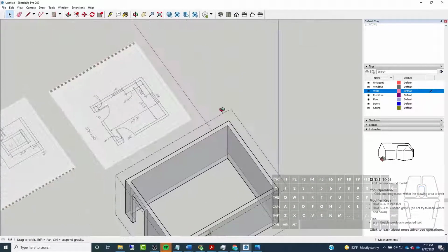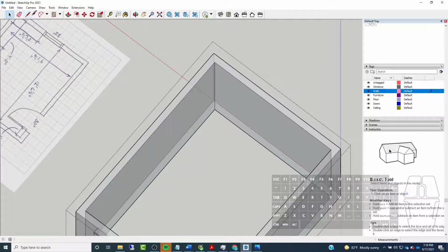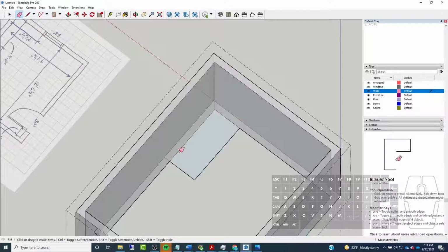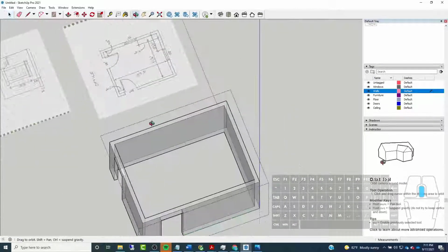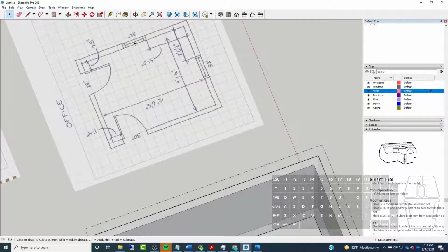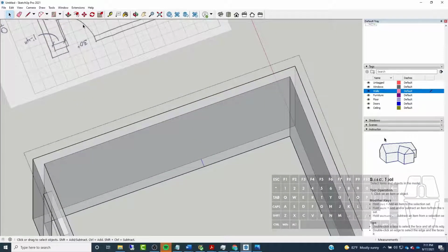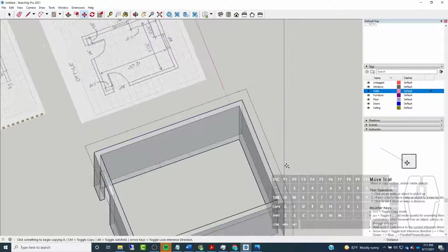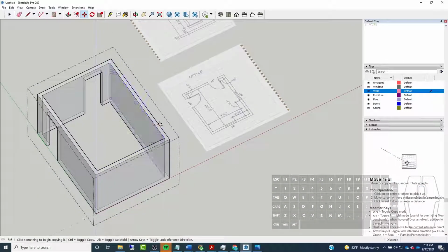Okay, so for my window now, starting at this wall, I'm going to do my dimension of 4 feet out. Then my casing, 4.5 inches. And then I'm going to draw my line through and just get rid of the extra pieces. So I just have my little line segment right there. Then my window is going to be 32 inches wide. So copy this 32 inches like that.